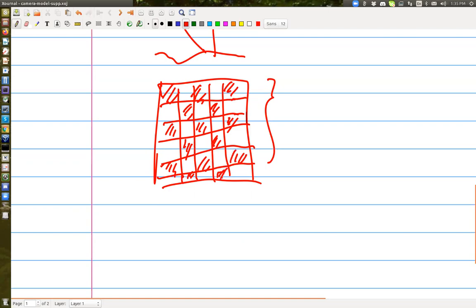See, I'm totally sleepy. Okay, so this is a pattern of 5 by 6, right? But note that the OpenCV code doing the calibration is trying to find the internal corners here. Therefore, the grid pattern that you give to it should be 4 by 5. Otherwise you won't be able to find it.